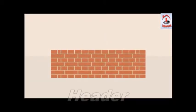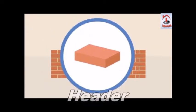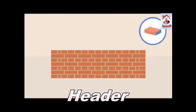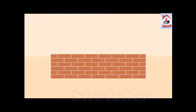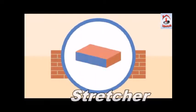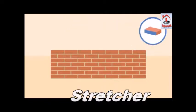A header is a brick laid horizontally, with its smallest surface toward the front of the wall. A course of headers is one in which all of the bricks are laid widthwise. A stretcher is a brick laid horizontally, with its longest surface towards the front of the wall. A course of stretchers is one in which all of the bricks are laid lengthwise.